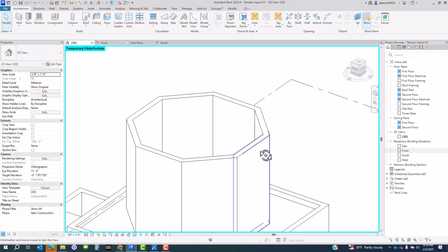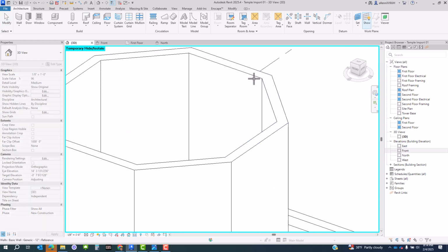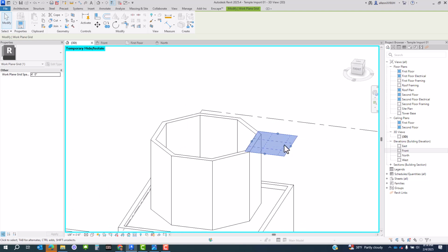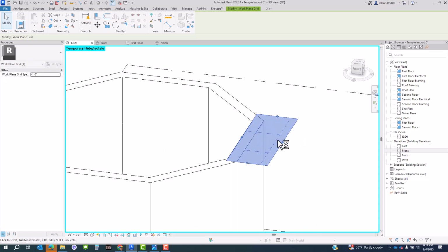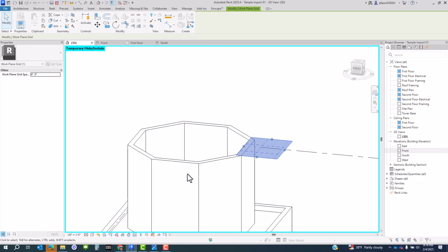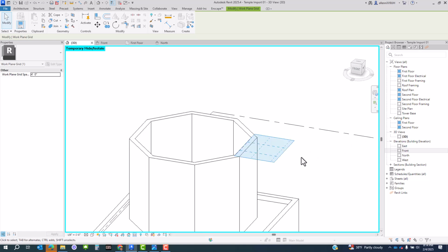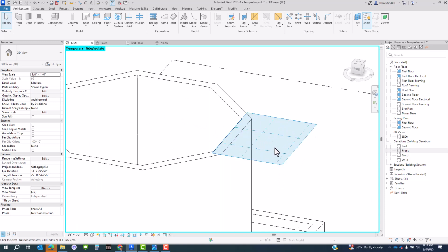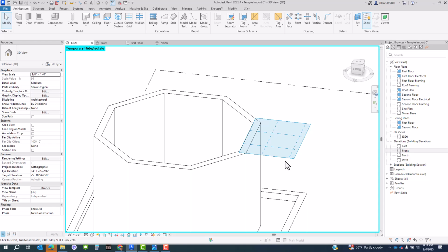Okay, I'll zoom into the top of the walls here, and we'll use Set, Pick a Plane. And as it's hovering over the top of any one of these walls, you can see it's highlighting just the top portion. And there it is. Sometimes when you select the top of a wall, it might only be as wide as that wall was. And so feel free to take the grips and expand it, and if visually that's helpful to you, it does make it seem like there's a bigger surface now to work on, the bigger that square is, or that plane.